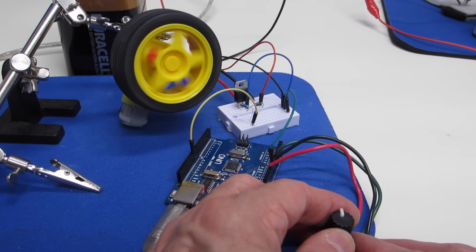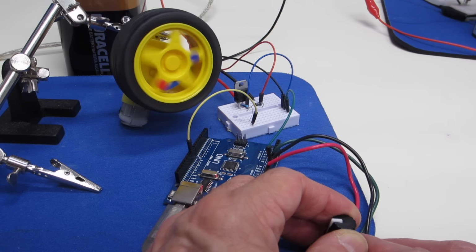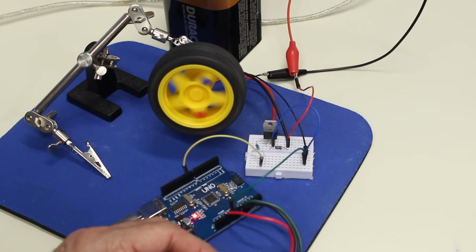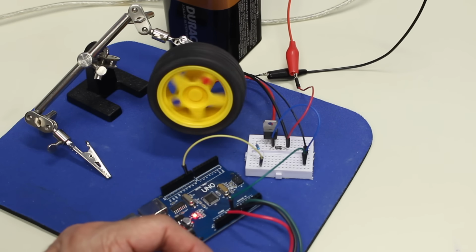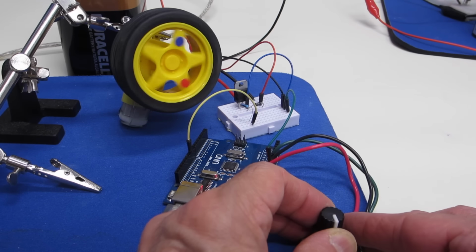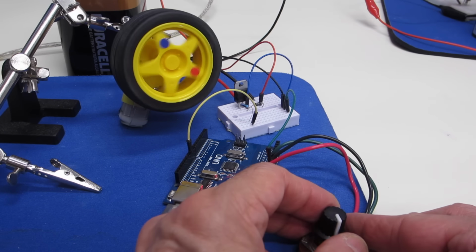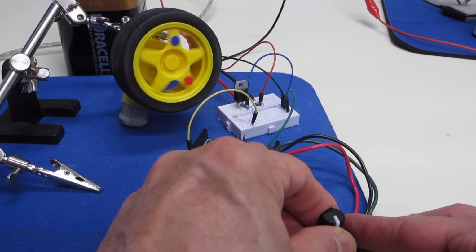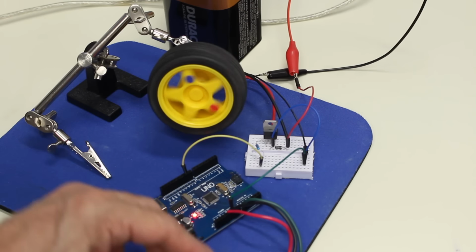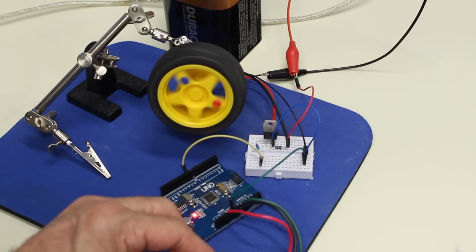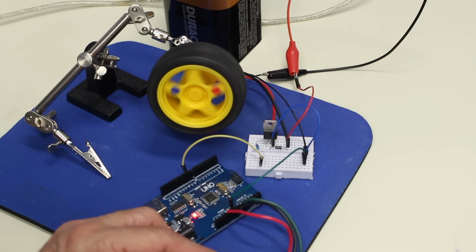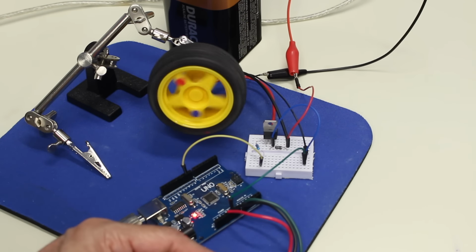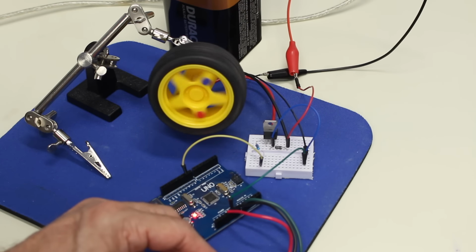And that's full speed right now. If I can bring the speed down. Get it to a low speed. And so it seems to work quite well. We're controlling the motor with pulse width modulation sent out to the base of the transistor. And once again, the motor is something that uses current and voltage the Arduino couldn't handle directly. So you could use this technique with bigger motors, with bigger transistors, and other than just having a simple potentiometer, of course, this could all be part of a simple robot circuit.